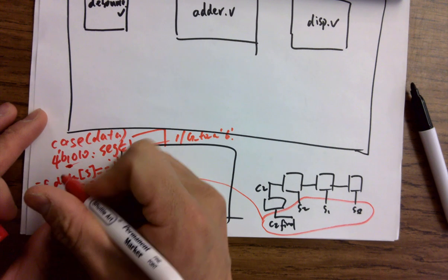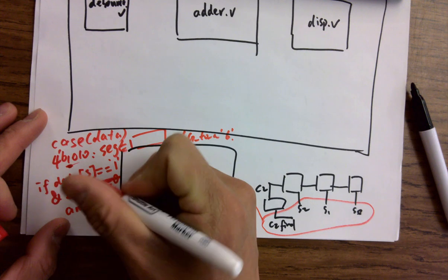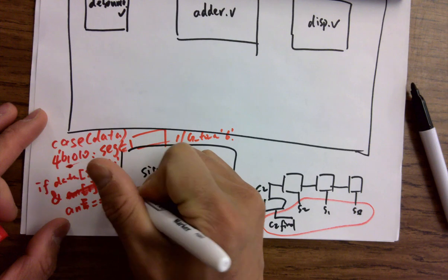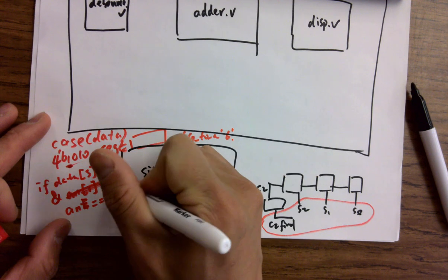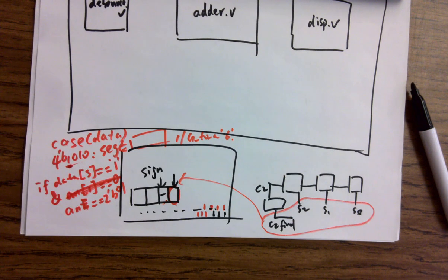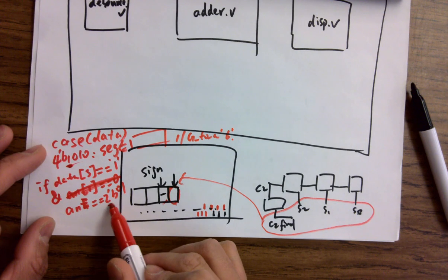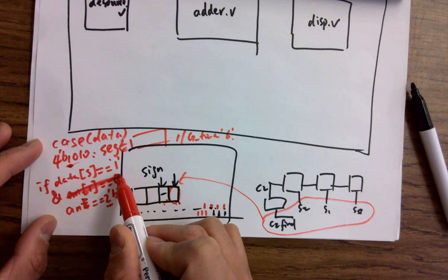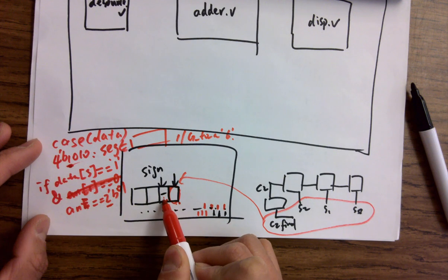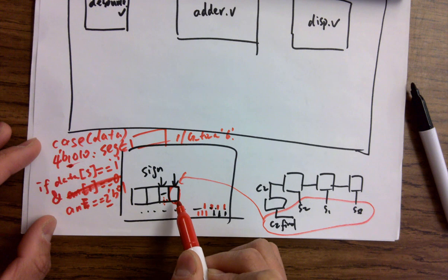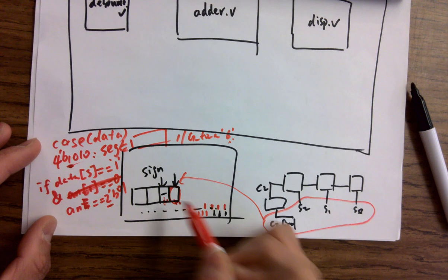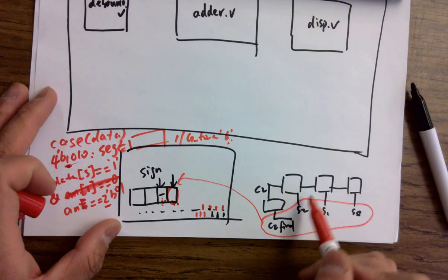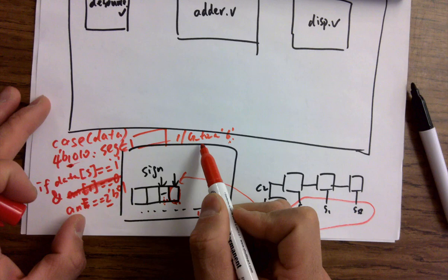So let's just use two digits for AN. If we define AN as 2 bits, so AN is a 2 digit binary number 0, 1, right? Which means this is on, this is off, and I'm gonna give a minus sign to this guy, right? But this digit should always display a 6 over here. That's a general picture of it. So we just need 4 bits, then we can display a number over here for the 7-segment display.